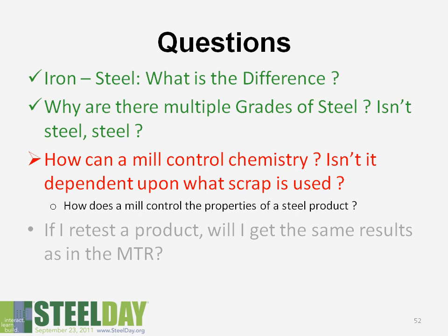Excuse me, Doug. Before we move on, can we address a couple of questions? Absolutely. One question here is why can't I get single angles in A992? You'd have to talk to the particular manufacturers or group of manufacturers who make the angle. A992 was originally intended to be used in structural wide flange shapes. That's where its origin was. Over time, the committee has expanded that to general application.